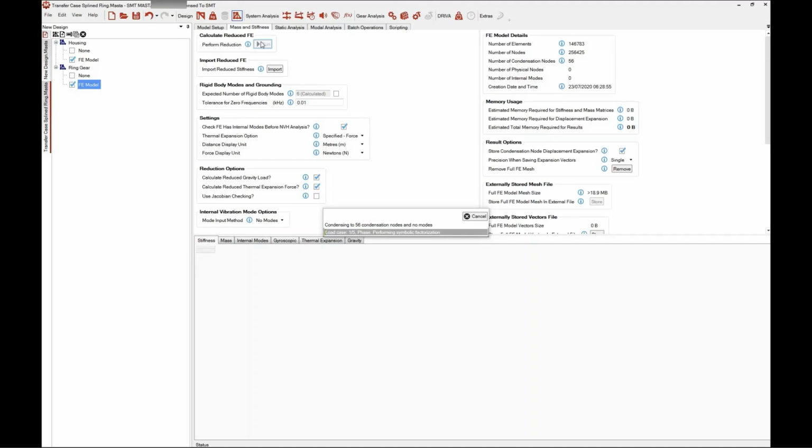By specifying it in this way, and using that spline component as a basis, we've actually created the entire contact between the two. So once this is run through, which should only take a couple of minutes, we will go into system deflection mode and just take a look at what we can actually see as a result of this analysis.